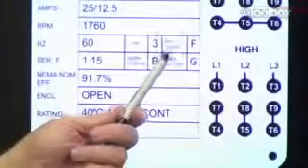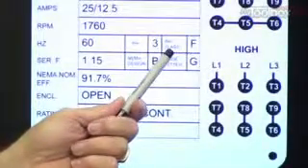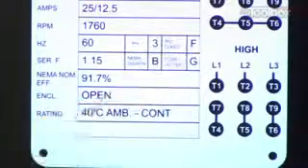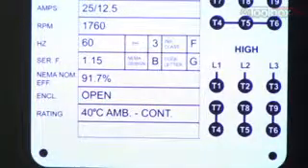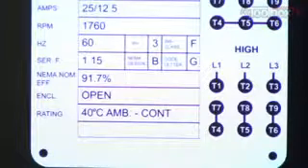Next thing I want to look at is the insulation class. This is insulation class F. There is a corresponding table from NEMA, and they tell you what that means, and it tells you what temperature the insulation for this motor will withstand. F is a pretty common one. H is for really high temperatures. So that tells you what kind of temperature this motor can operate at.